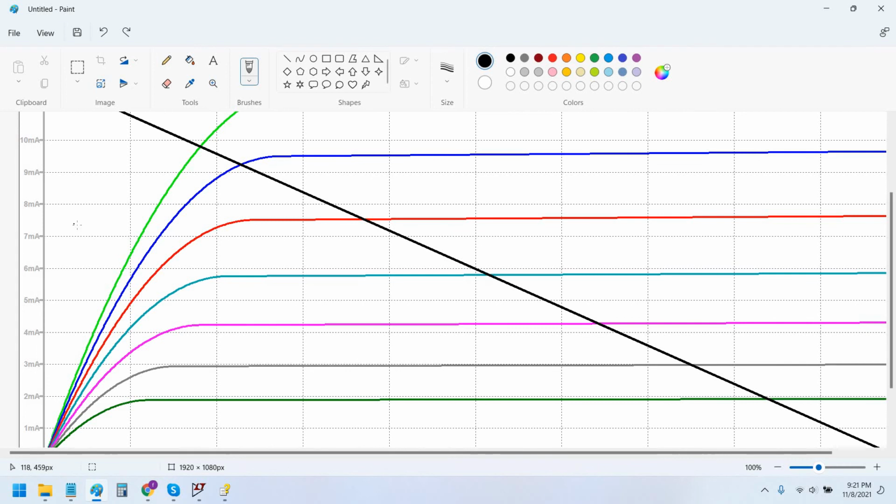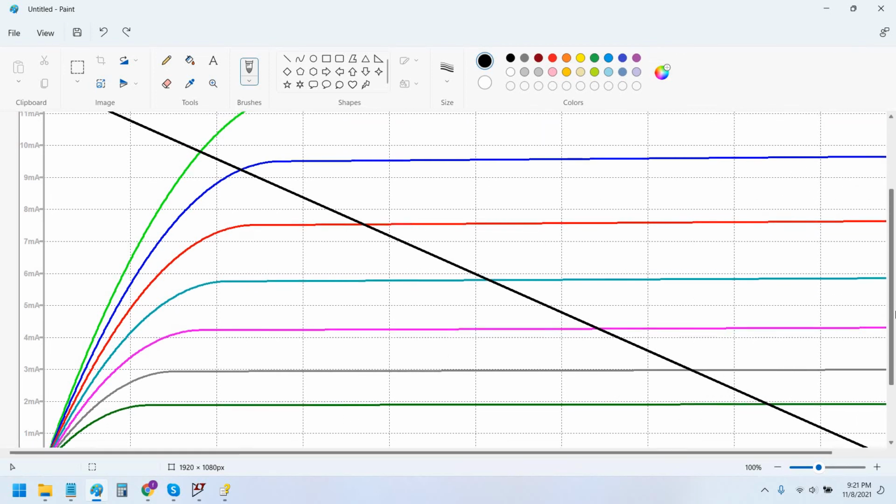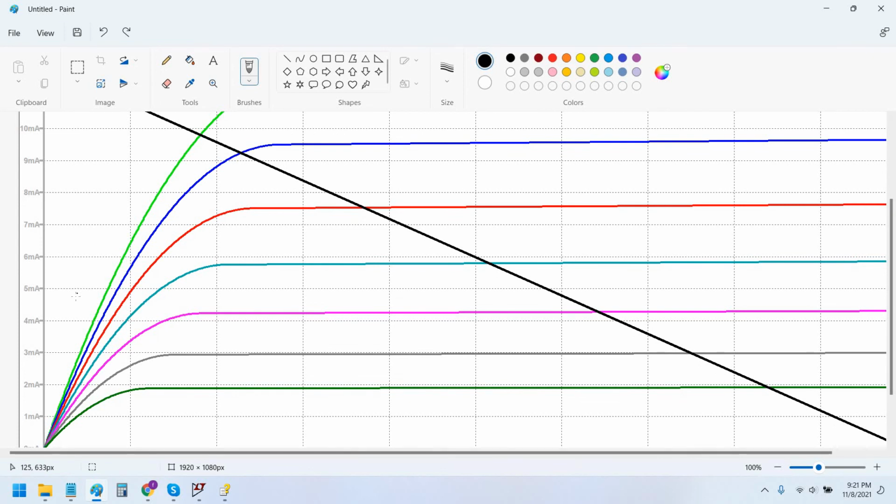This is because we select minimal drain current to avoid maximum power dissipation in the transistor itself, which would cause heat dissipation. So we would select the minimum possible value of IDS so that the voltage swing would not cut off at the quiescent point.